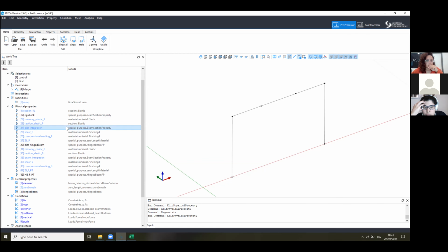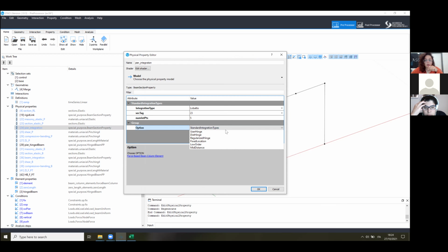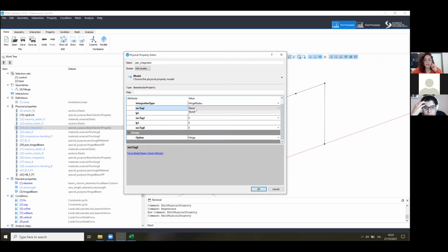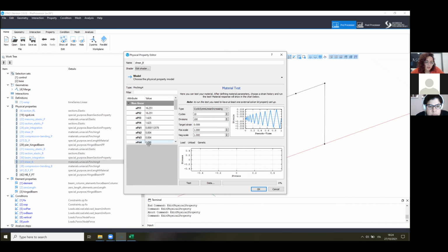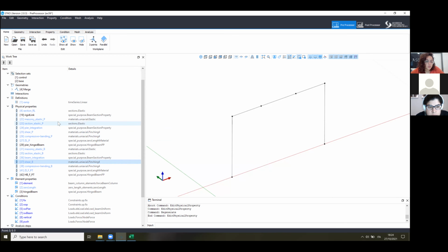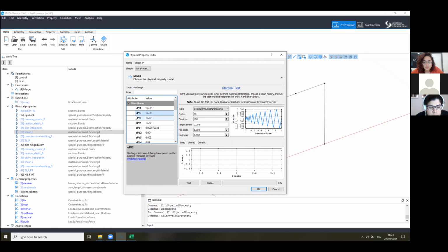So instead of using the beam section property here, we could have picked the hinge and then here selected the nonlinear materials, nonlinear fiber sections for the extremities and the elastic section for the center, and applied a plastic length, a length of the plastic hinge. And the same you do for the beam. Just for you to notice, in terms of difference, this is the maximum shear that I had applied to the beam, and this is the maximum shear that I applied to the pier. So my pier is way more resistant than my beam.